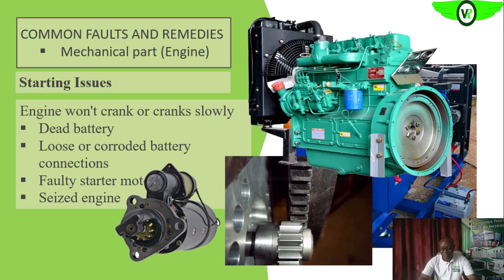When you see such, just firm the contact, or you can go and feel it to see if it is free or not. If it is free, you can firm up the contact. Then if the starting motor is faulty, you either replace or you repair.